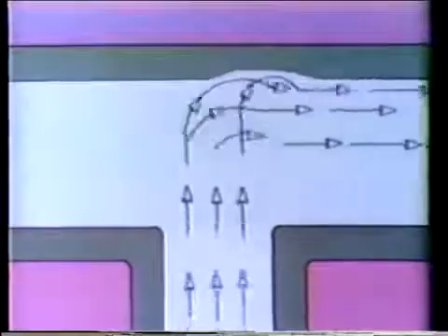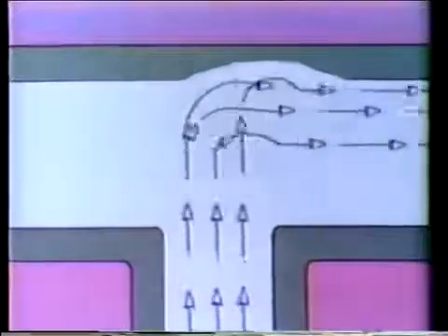Now, erosion is a bigger problem with tubes and headers than it is for the larger vessels, because here the speed of the water or steam flow is greater. When this high velocity flow enters a header, it must make a turn, and this forces it against the header wall. Over a long period of time, this causes erosion.